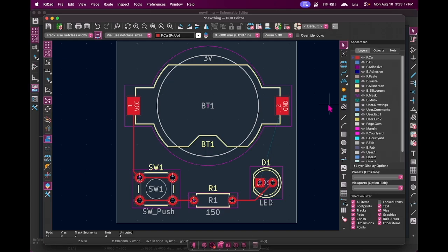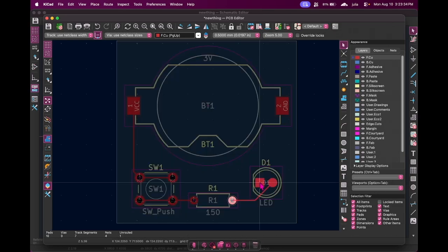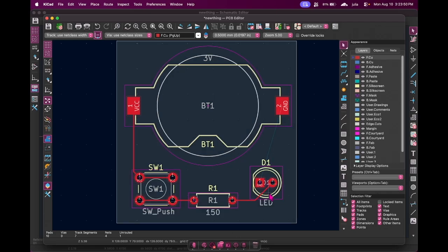I have a question. I want to move everything more compactly, but it doesn't move the traces with it. Is there any way to fix that? No. Even if you select the whole component and click D, it kind of moves the traces, but not really. It's in a really dumb way. If I want to move it down here, it doesn't move the trace with it, and you can see a green line saying this trace is intersecting. If you try to put it there, it says no, we're not doing that, and it goes back to where it originally was. If it would move the trace with it, it would be nice, but it doesn't. It pretends to move it. It's faking.